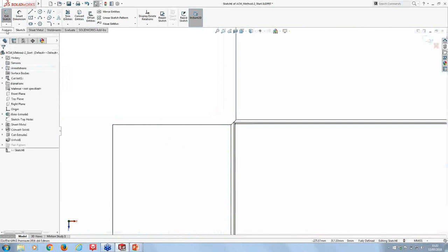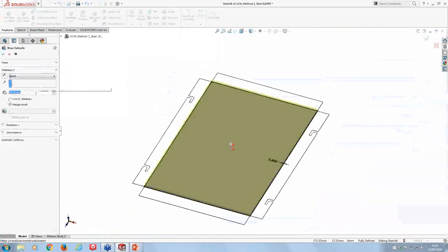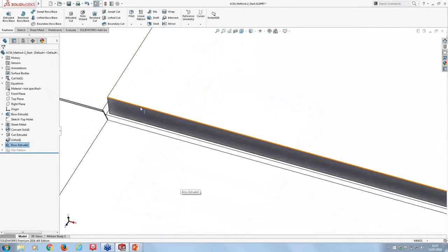And let's just do an extrude on this. Let's just set that to 4.5 mil. Now, of course, on the edge detail here, we would actually have maybe a chamfer detail, depending on what tool we'd used. So let's just use the chamfer tool on here.